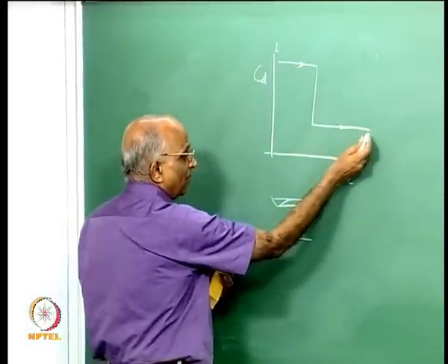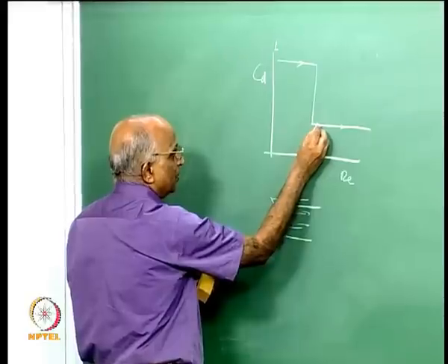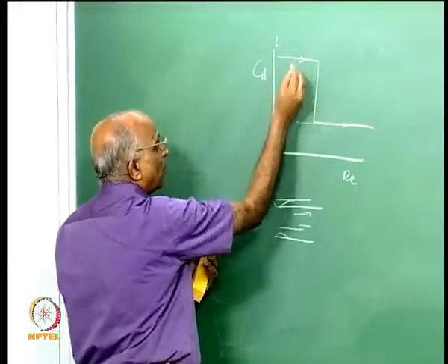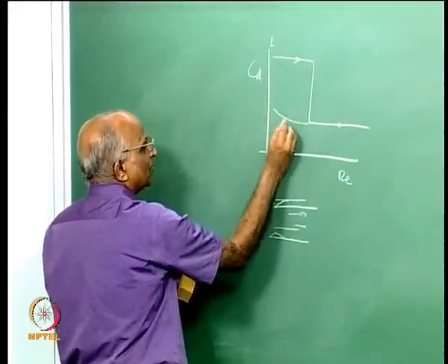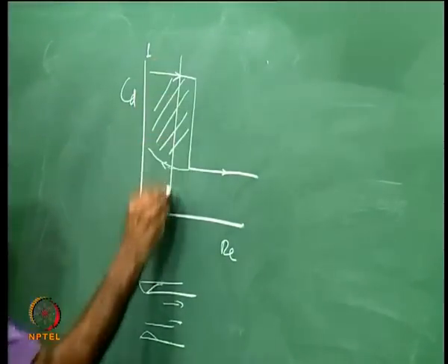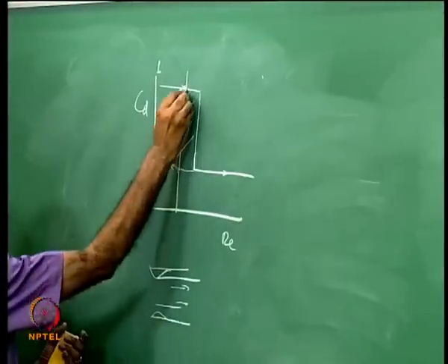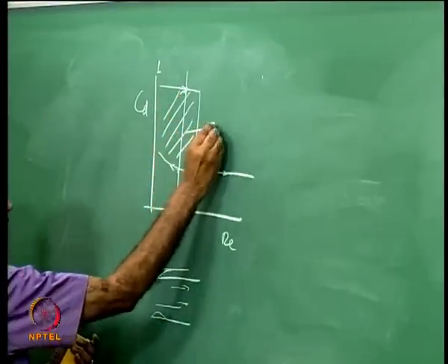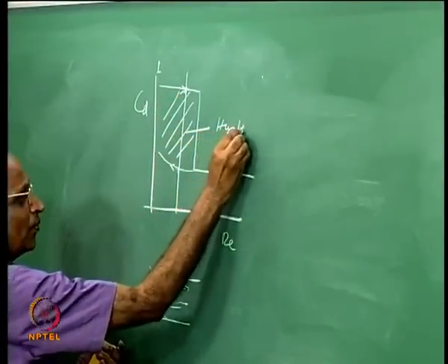After doing this, I want to throttle it back, I reduce the pressure, it does not go back over here, it goes back like this. That means I have a zone which for the same value of Reynolds number can give me 2 values of CD, and this zone is known as the hysteresis zone.